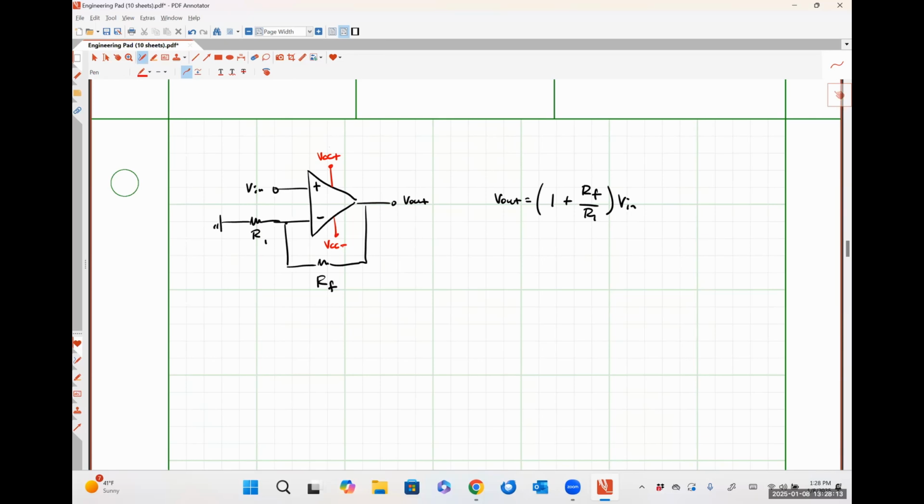So that DC offset, and the fact that it's also going to be amplified, might push the output of our system to a point where the amplifier effectively becomes saturated. What that means is that any increase in input signal does not cause a correlated increase in the output. It would be like having a threshold on the output, like we wouldn't be able to detect that at a certain point. Exactly right.